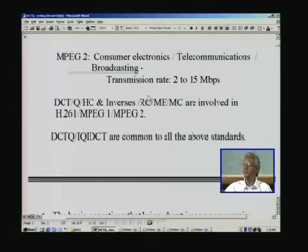What we are going to do is only DCTQ to start with, and IQ IDCT has also been done, but we are going to use only the end result because the design is quite involved, and we will have to restrict it, and even this goes to some 124,000 gates or so for DCTQ alone. Then comes what is called motion estimation and motion compensation.